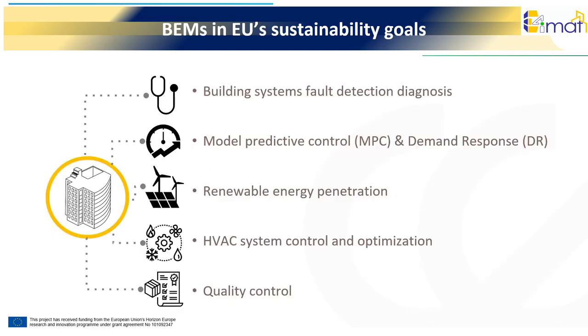The use of calibrated BEMs is not constrained to measurement and verification purposes only, nor to the design of energy-saving strategies. Additionally, when used in conjunction with the building management system, BMS, a calibrated BEM can be applied as a fault diagnostic tool dedicated to analyzing the performance of components from the HVAC system. In similar fashion, it can be used for model predictive control, MPC, using its calculated predictions as inputs for the building management system, which in turn allows for the application of demand response strategies or renewable energy penetration.